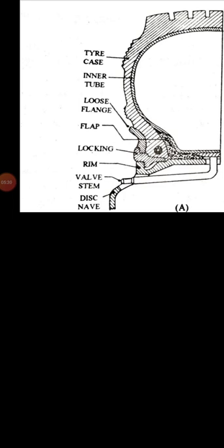The tube is manufactured from rubber sheets, basically pure, good quality rubber material, which is shaped on a former and cured. It is totally a curved shape. The tube is also constructed about 10 to 15% undersized, because when we expand the air, the volume of the tube will expand.